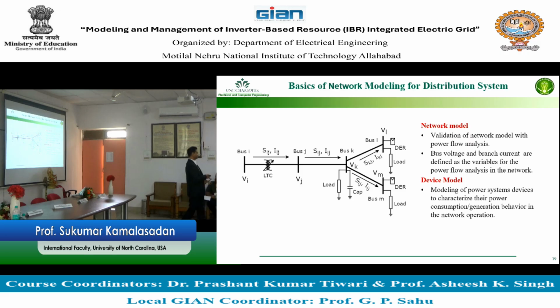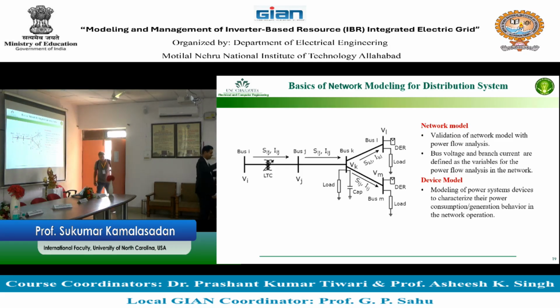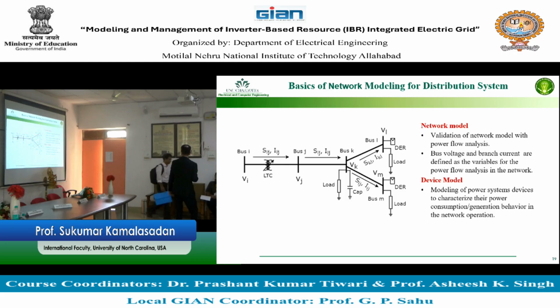There is another type of capacitors which is connected to the point to change the voltage, which are called, it's not variable, it's the same capacitor, but they're called switched capacitor. How does that work? It works based on switching in and switching out. So those capacitors are in or out. It's not varying or variable, but number or no number, right? That's like a switched capacitor. So switching of the capacitor can be done based on voltage switching or current switching.